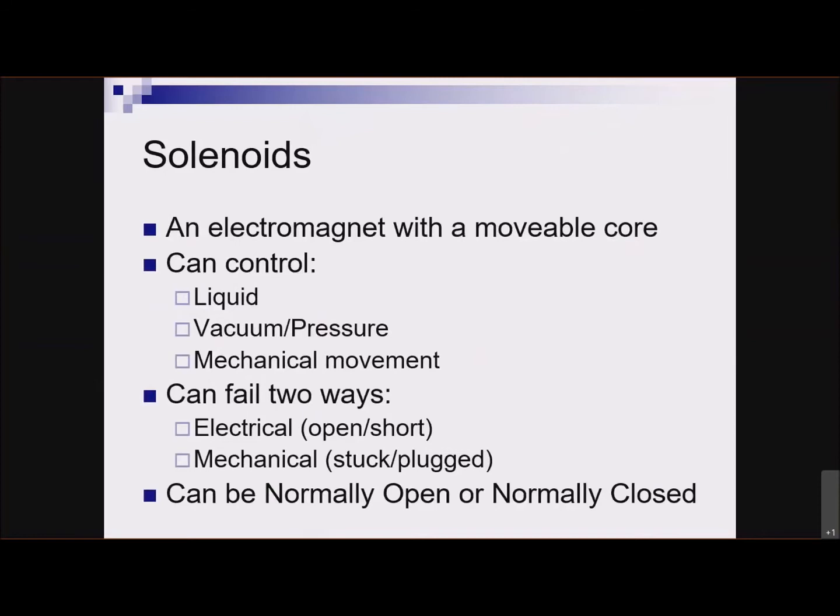And that, over the years, I think has led people to be really confused because a lot of times the starter relay and the starter solenoid are kind of a one-piece thing mounted down on the starter, and it's a big heavy-duty thing. But that's not the only kind of solenoid on the car. In fact, that's very rare.